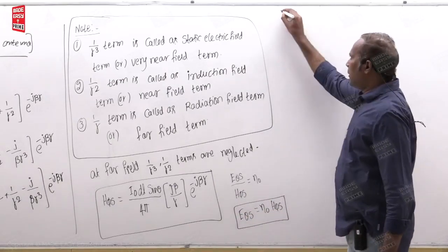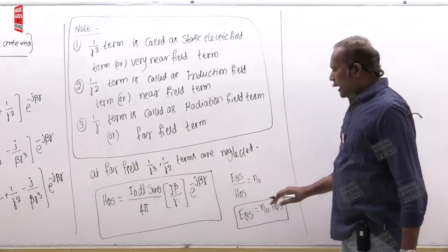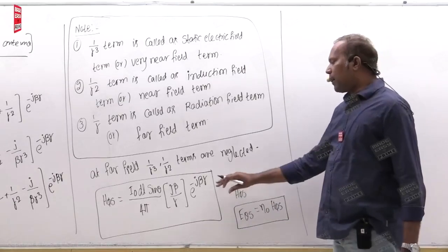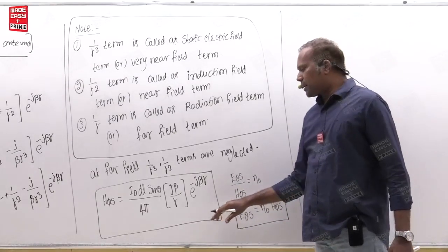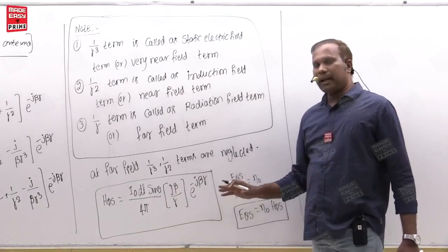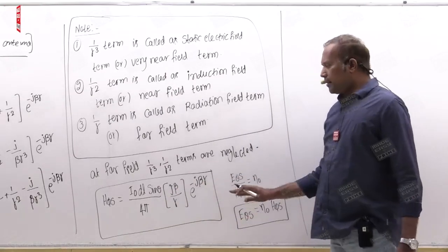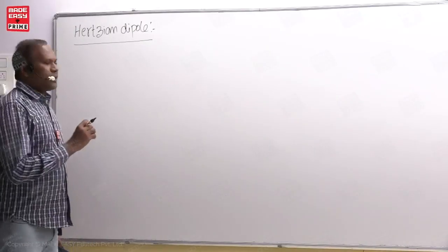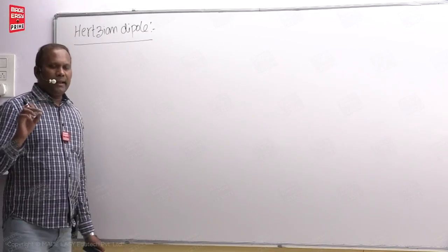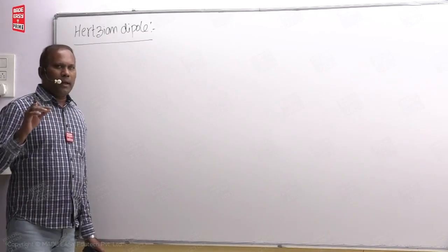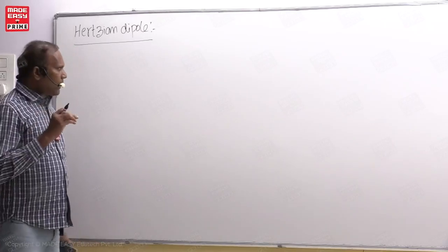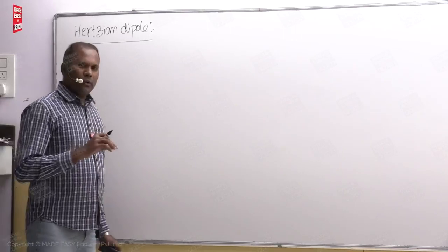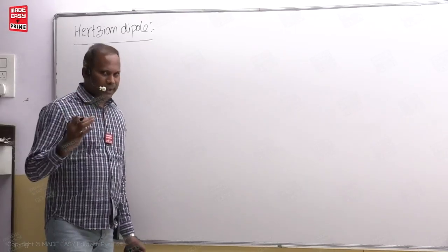Okay, students. If you remember this equation, no need to remember the electric field equation at far field. Anyway, for objective questions, they may not ask this also, but for conventional questions, you need this. We will be talking of that one. Okay. So students, we have seen the magnetic field intensity phi component. You have remembered. I told you to remember. Then E theta s divided by H phi s is equal to eta, then E theta s is equal to eta into H phi s.